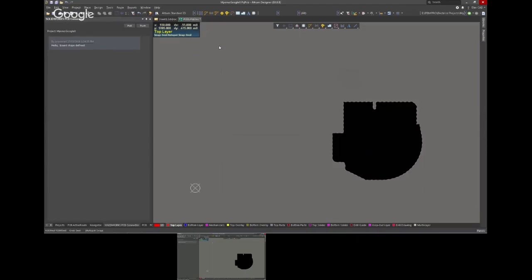Then it's just an outline, then I have to define the board shape from the outline. It takes about 5 minutes. Not drawing it, that's with a DXF. Good luck if I'm going to draw this in Altium Designer. It can take me up to like 4 hours because the tool is not meant to draw arcs. We know it's not. So it can be very, very painful to draw this in Altium Designer if I don't have a DXF.